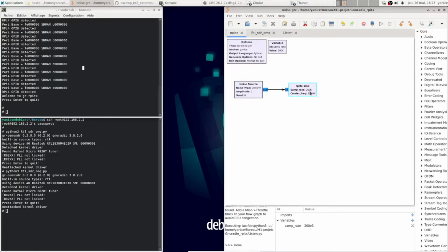200k samples per second sample rate, because this is the maximum value that the DMA will accept. Beyond this value, the samples are not quite right. The data are just doing anything but what we want.